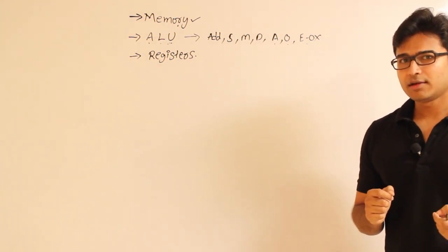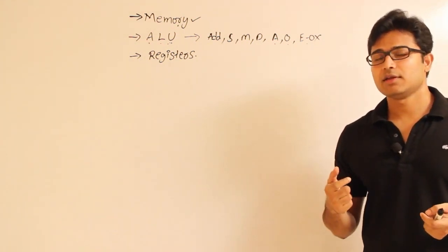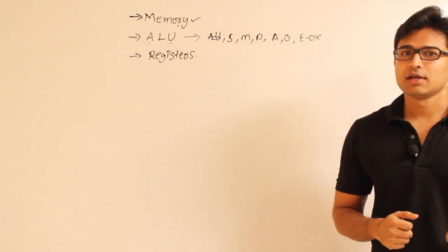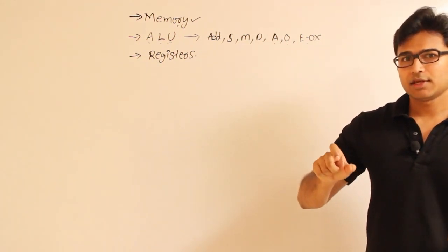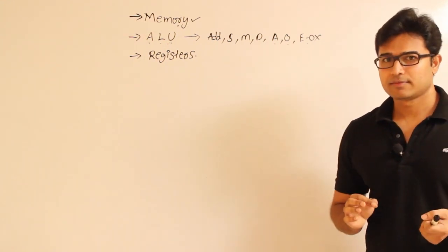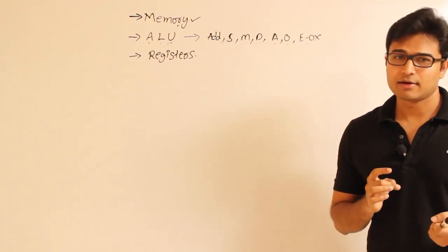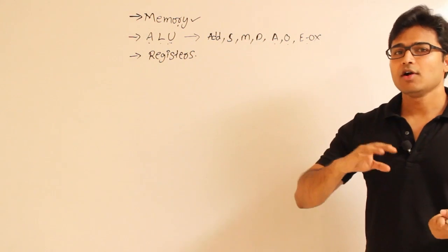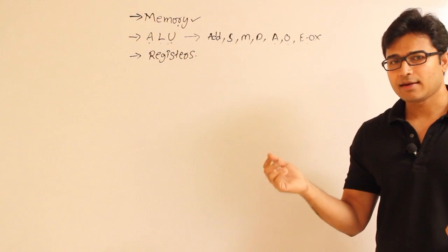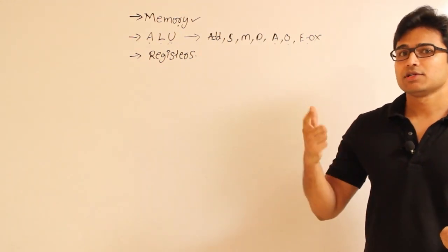And also along with that, we can use these flip-flops in such a way that they are going to act as binary counters. Now what is the advantage of it? By connecting them in such a way that they act as a binary counter, as a shift register, as well as parallel load and parallel read, we can use a register for parallel loading and then reading parallelly from all the bits at the same time, as well as for shift operations.